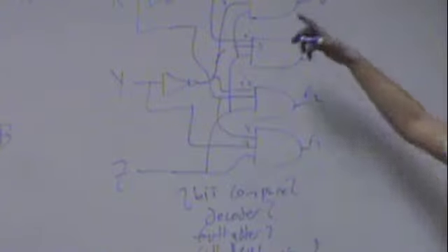And then a subtractor is an adder, but one of the inputs is inverted, and then you add one. Yeah, and it also, same thing, it doesn't have 4 outputs. That'd be just too many. So it's either a 2-bit compare or it's a decoder. So, why is it a decoder? A compare would only have 1 output, you're absolutely right. It would just have a, is it compared or is it not? Yeah. And then the Z in this case, for the decoder, what it does is it decodes what these are.